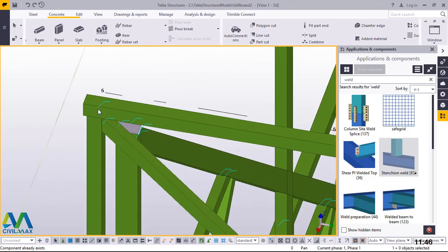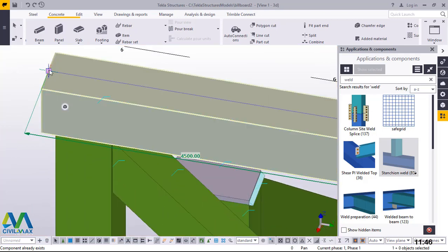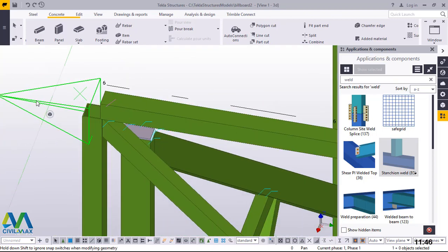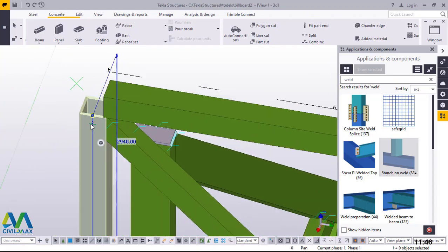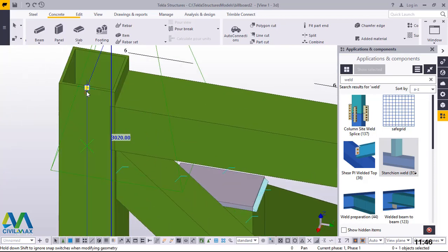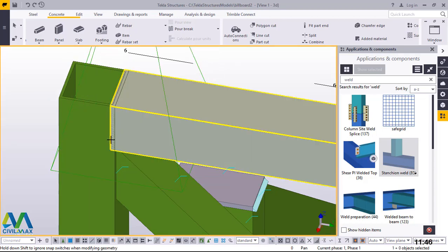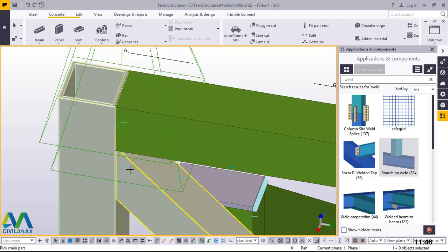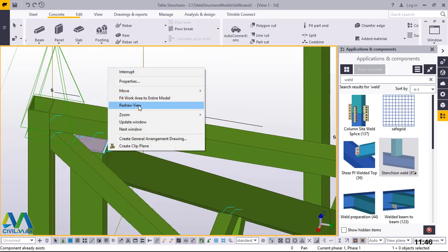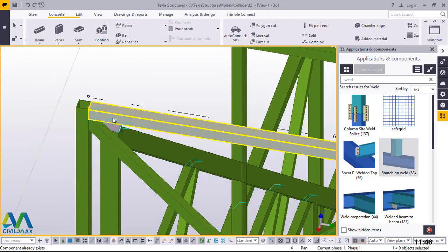And we'll do the same thing here. Just drag. Bring it somewhere there. Delete this connection first because it will restrict your extension of any member. Then just drag that up. Make sure it is on the straight line. Make that part our datum. Then I'll connect that to that, weld this to this. Perfect. Welding already exists on that spot. Right click and click redraw. We are done with that part.